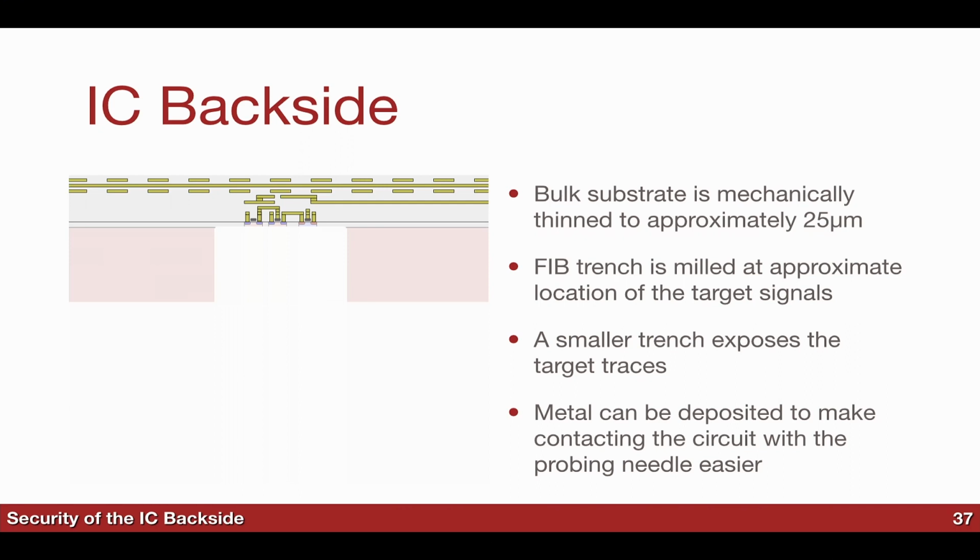Now we wanted to target the wire in the middle, so we have to remove stuff just in that area, and then we deposit some metal. Now you see that signal is exposed to the outside world, and we can come in with a probing needle, also approximately to scale. This is a 1 micrometer probing needle that you can't see with your eye, but it's still orders of magnitude bigger than the actual transistors there.